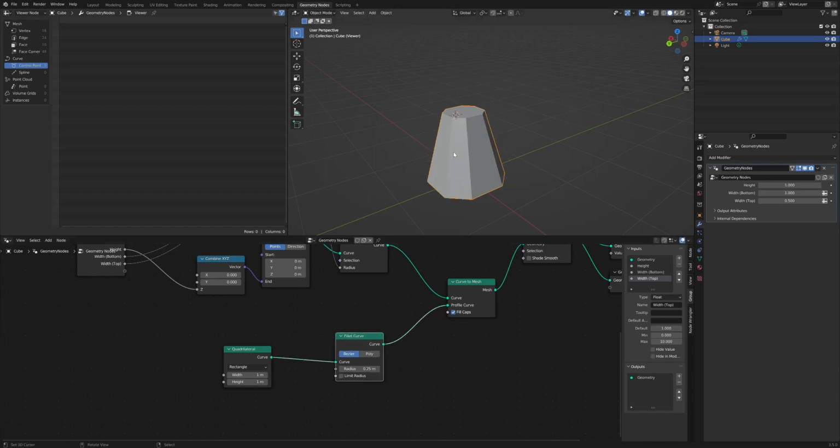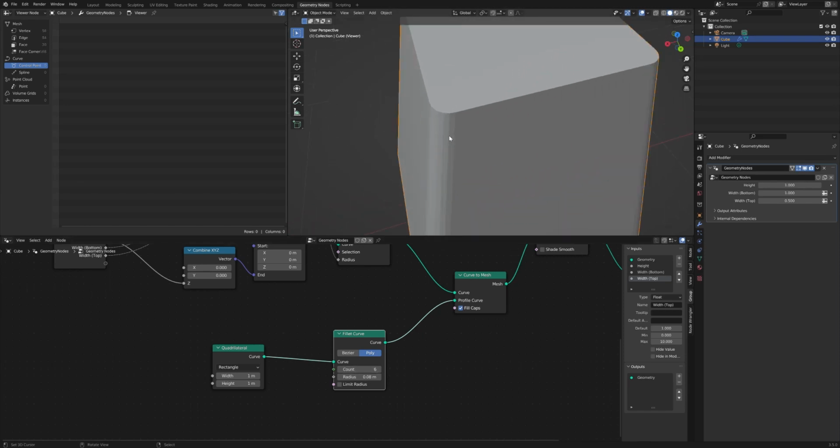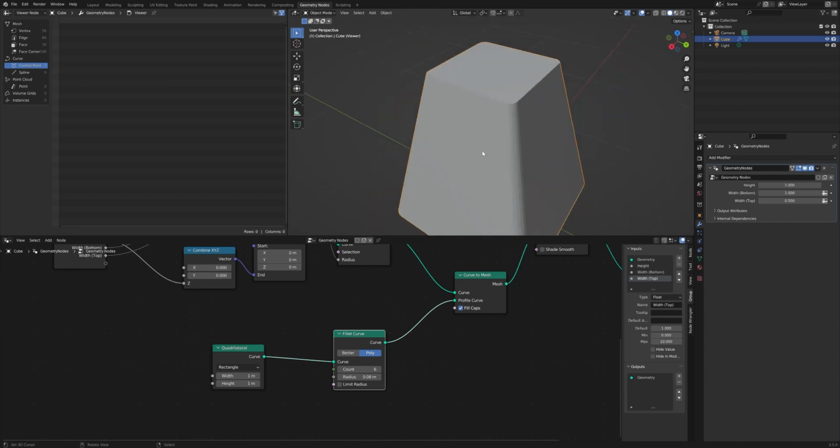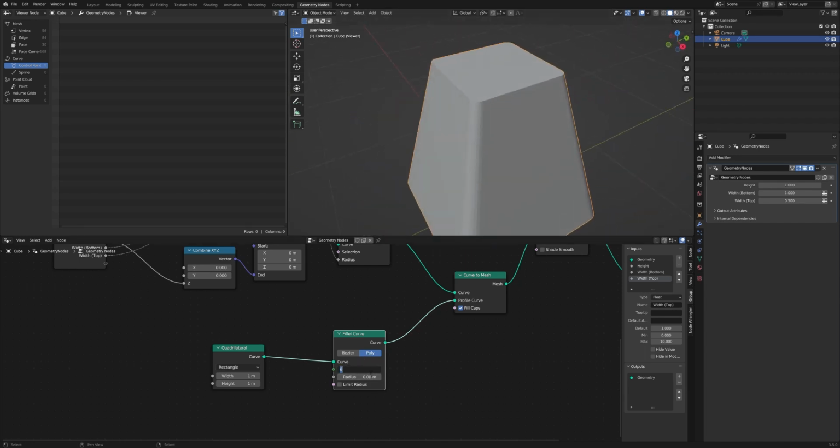And so now you'll notice straight away it's chopping off the corner. We can reduce that radius, and then in addition to that, we can change it to poly, and then have a higher count here. And what that does is it breaks it up into lots of different bits. And that makes it much easier to define a smoother radius, should we say.